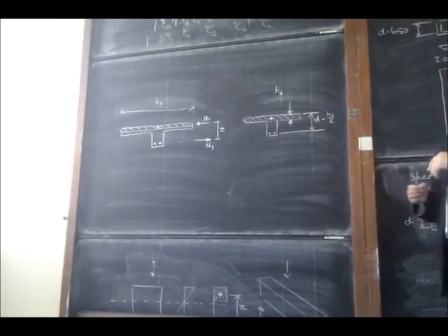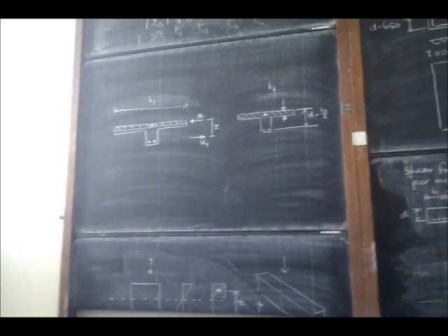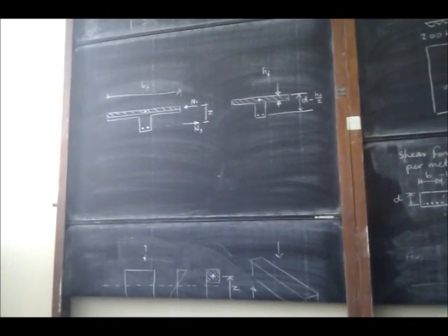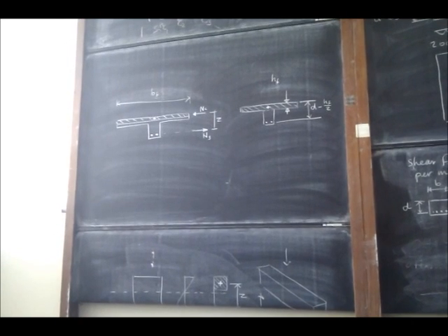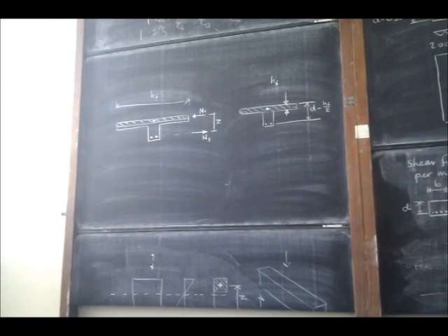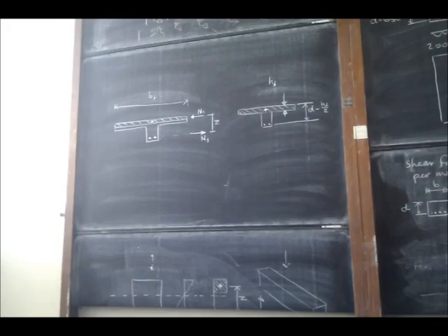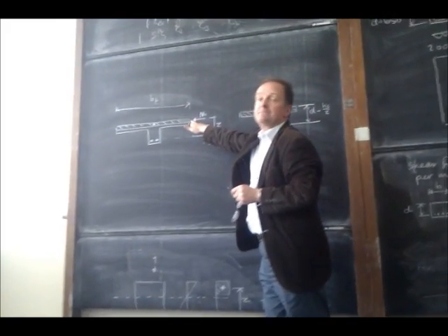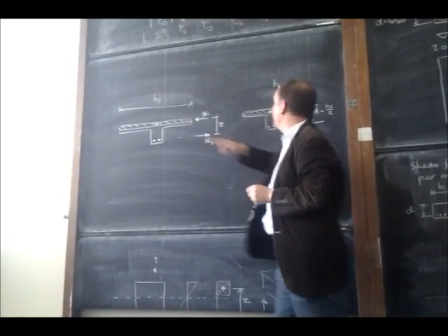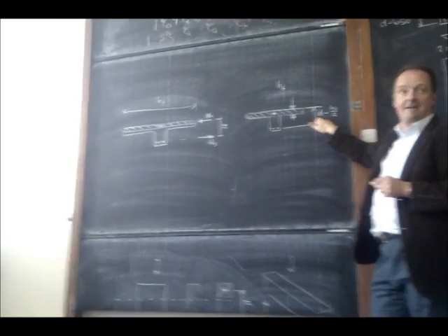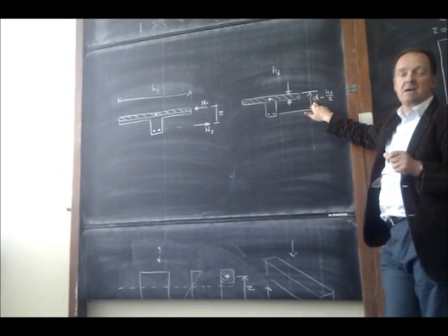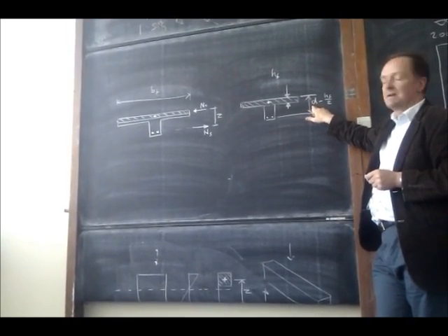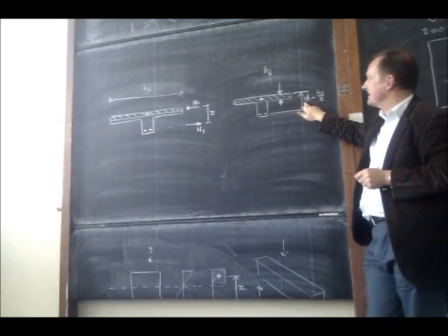You can then work out the total force available in the flange. You could then balance that with some force in the steel to determine a moment. If that moment's more than you need for the applied moments, and you're not using the whole of the flange, you're back to this scenario, and the assumption that you made about Z is conservative. So you're making slightly conservative assumptions just to save you tedious calculation.